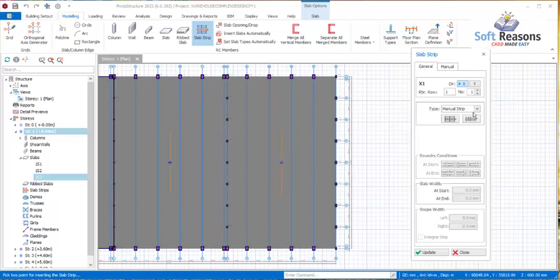Because if you use the analytical method of analysis for any slab on grade, it's not going to work. So in that case we use FE strips, like for floating raft and raft on beam. All of these are substructure. They are located beneath the soil, so you use the FE method of analysis and not analytical. Analytical is used for suspended slab. All right, so let us make progress.